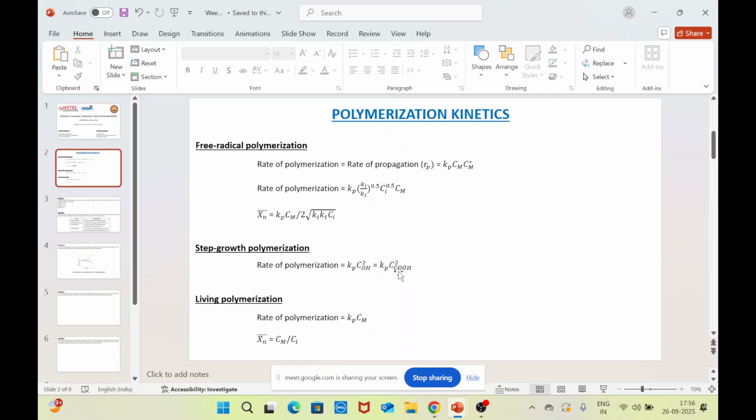Because of this external heating as well as the viscous dissipation and the friction that the pellet encounters, the polymer pellet is heated and it forms a molten polymer. This molten polymer reaches the end of the screw and is forced through the die to achieve the desired shape. Once it achieves the desired shape, it is cooled and solidified. Now, this is about only the process.